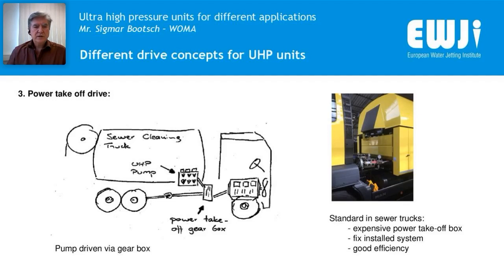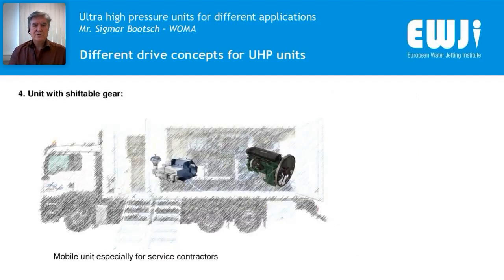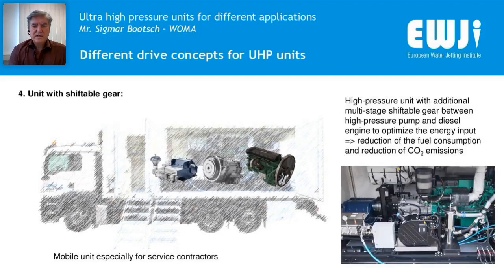Another solution, and a very interesting solution, especially for service contractors, is the drive concept with a shiftable gear. That means an additional multi-stage shiftable gear is installed between the high pressure pump and the diesel engine. So with this drive concept, the energy input is optimized and thereby the operational costs are reduced for the specific application.